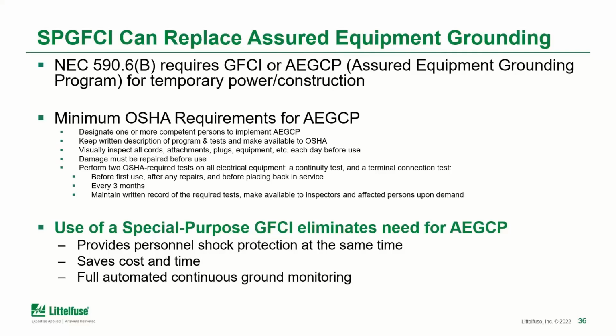Now, if you have a special purpose GFCI application, it actually takes care of, or eliminates maybe is not the word some would use, but it takes care of the same steps, because it's proving that the ground is there and that it has a low impedance. So it's really doing this in an automated fashion. And so it takes care of the assured equipment grounding, meaning that you don't have to do all those steps manually. So if you're using that program on some of the portable equipment, perhaps in construction sites, a special purpose GFCI actually would take care of that in an automated fashion.